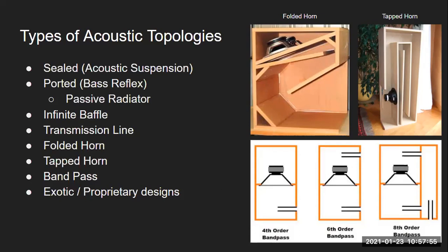A tapped horn is sort of an advancement on that, made famous by Danley, and that's an interesting one where it uses quarter wavelength amplification with a horn geometry, sort of like a hybrid transmission line folded horn-ish. So that's a common one, especially in large format sound.